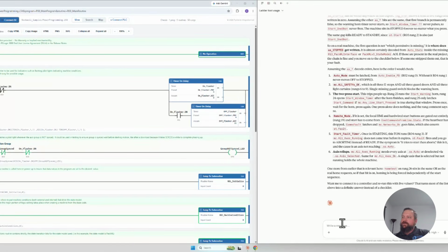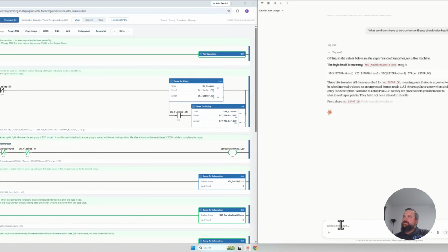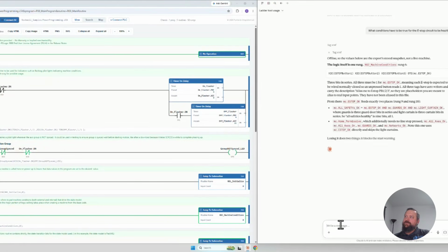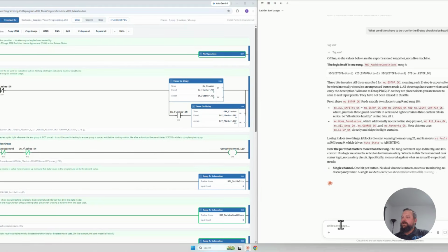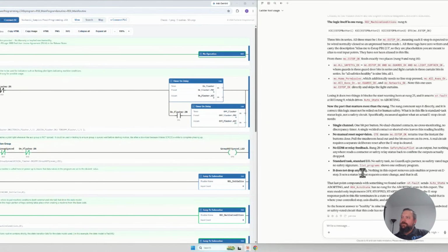So let's try, let's see, the e-stop circuit question. Pretty common thing that goes wrong with equipment is e-stop issues or safety issues. Can be lots of different things on the safety side that can cause problems, but in the program what we want to try and do is direct them to the actual issue, whether it's an e-stop or door switch or safety monitor itself. That's why it's always good to have that feedback back to the PLC for your e-stops and safety monitors, or else do your safety logic right in the PLC. Although I do have some mixed feelings on that, on whether it should be all electrical or the programming should be allowed.